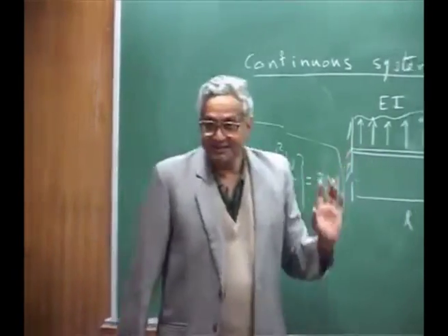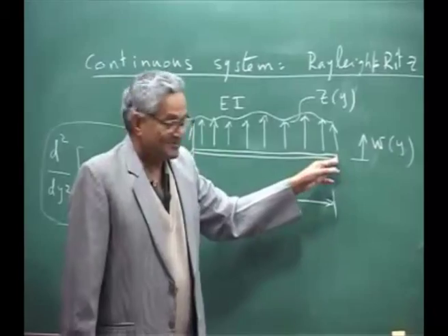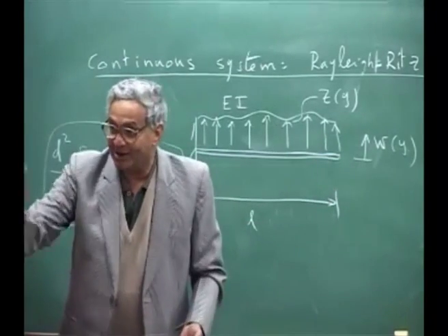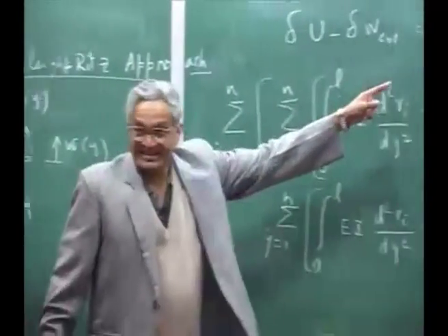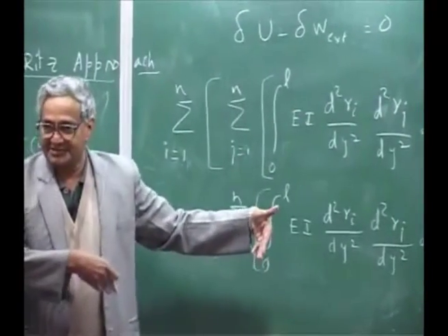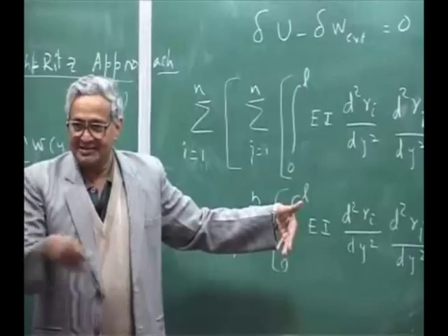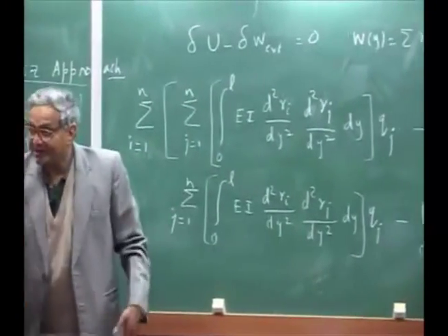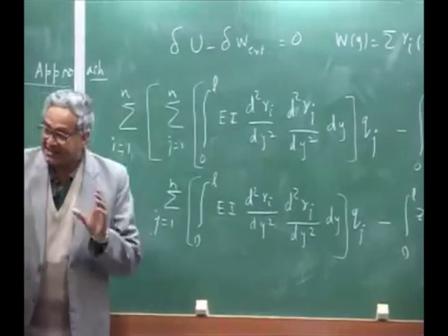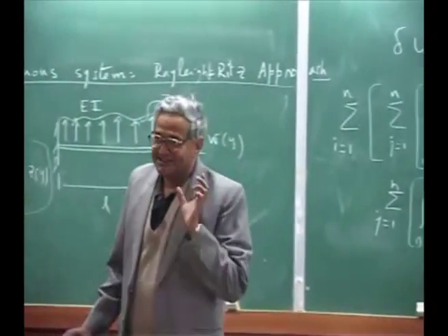Whereas here what we have done is, we are not bothered about the force boundary condition at all. We simply used geometric boundary conditions. Okay, like displacement and slope 0, and it is also differentiable only to lower order. So that is the attractiveness of the energy method.